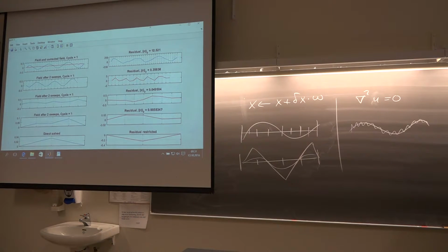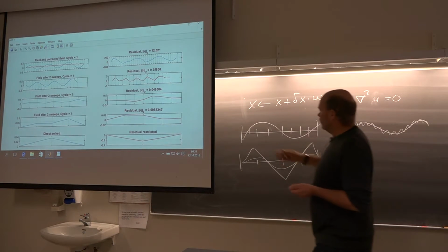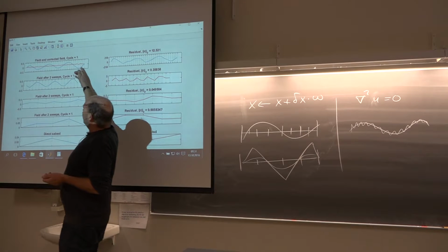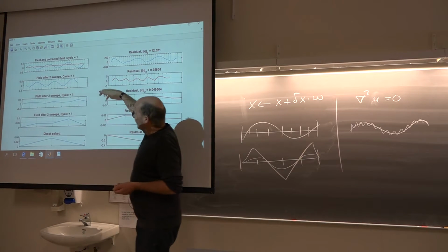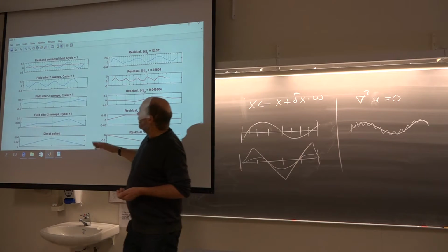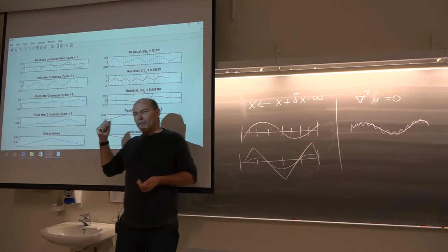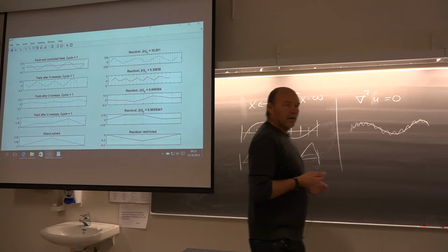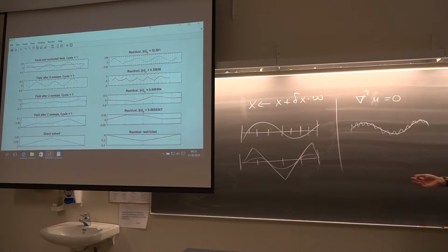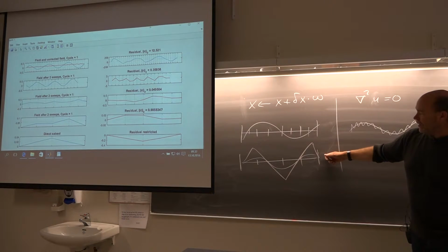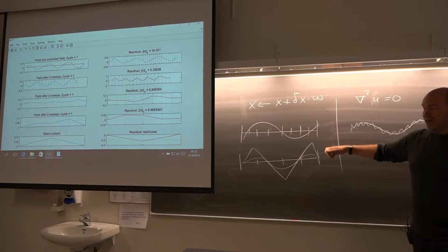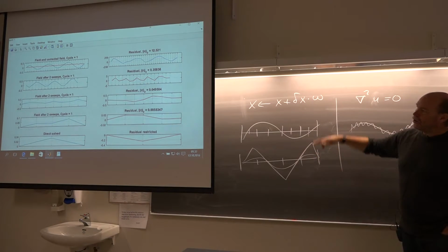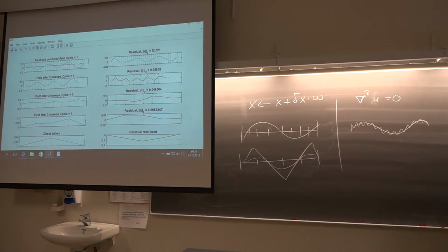And there you see the effect of just one cycle. You see a lot of the noise of the error that we had up here will now be removed. And the number of calculations down here is very few compared to the fine mesh. Remember, this is a one-dimensional demonstration program. Think in 2 dimensions or even in 3 dimensions. The coarse mesh here in 2D will be 1/4 of the fine mesh. In 3 dimensions, it will be 1/8 of the number of unknowns. So the amount of work on the coarse meshes is not much.